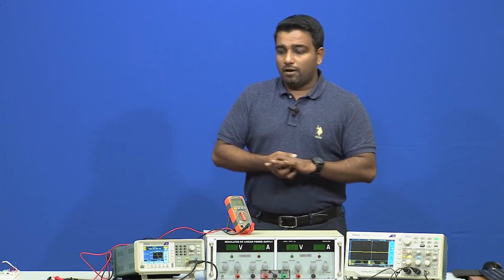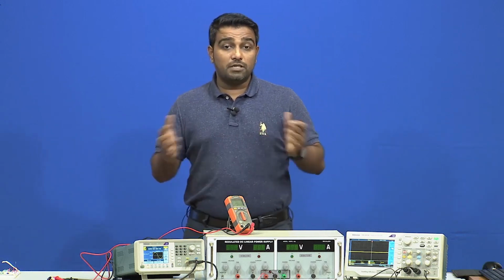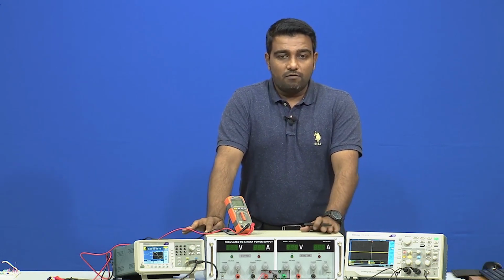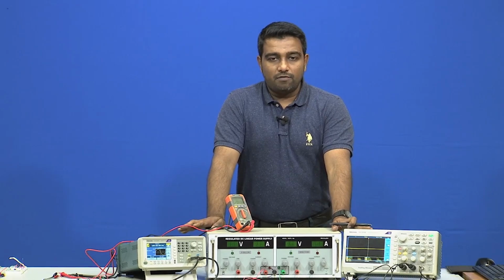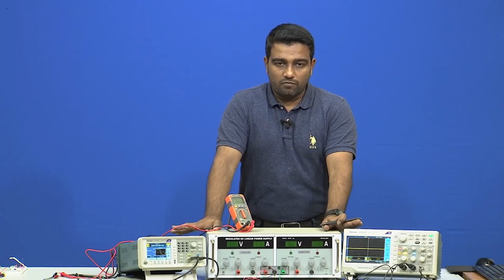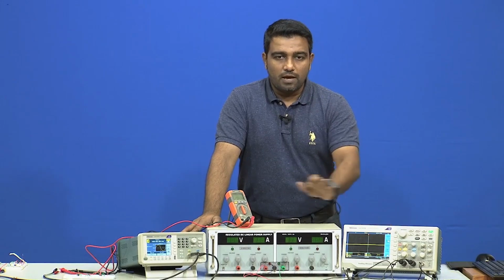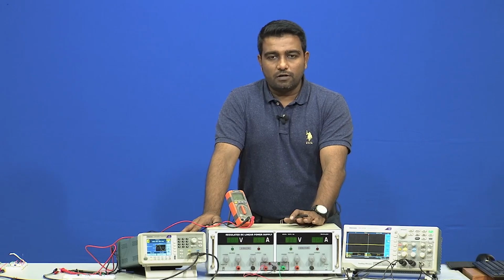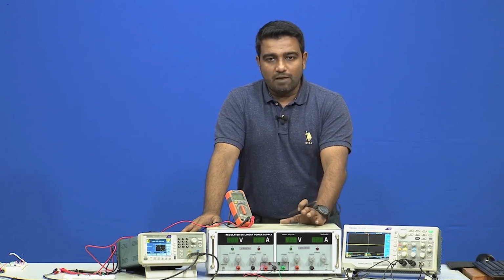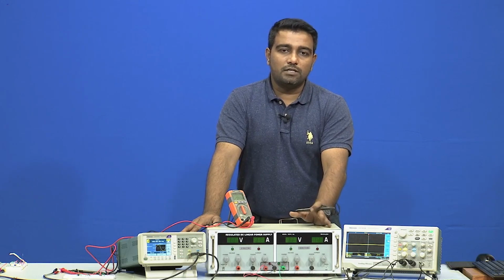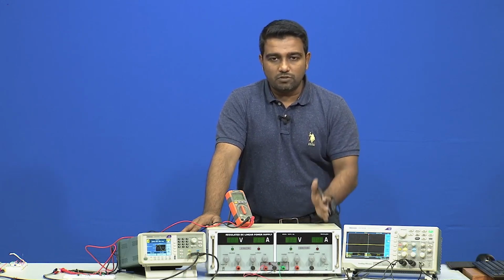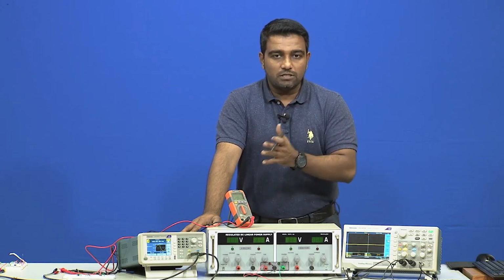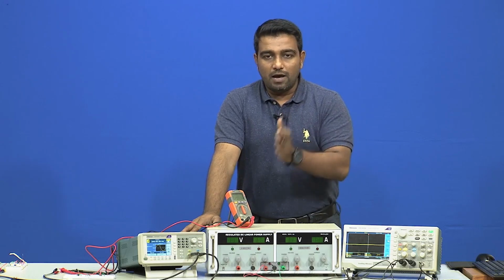We have also seen how we can measure using the equipment that we have: a DC power supply, a function generator, and an oscilloscope. So, this is your function generator, this is your oscilloscope, and this is your DC power supply. We took the help of a breadboard on which we mounted the circuit, and we saw the change in the output signal when we apply some input signal, how we can measure the change in voltages, and how we can calculate the IB.